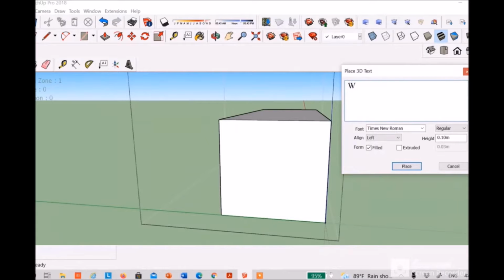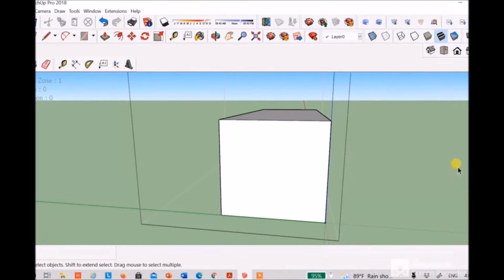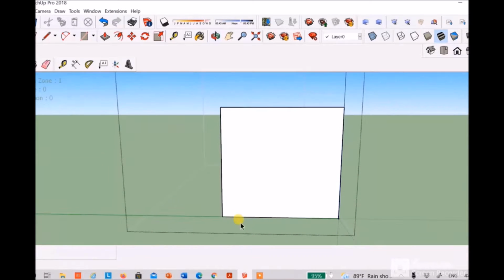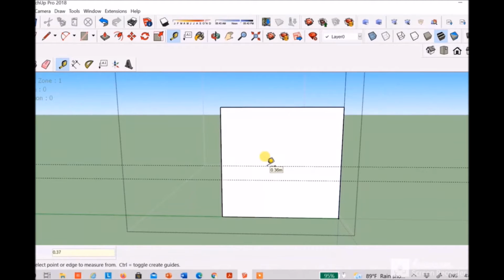We start with the west facade, and we give the name wall 1 to this section. This wall has 16 sections. We select the tape measuring tool from the toolbar and enter the length from floor to work plane as 1 meter, and we divide the work plane to ceiling into 5 horizontal divisions of 0.37 meter each,